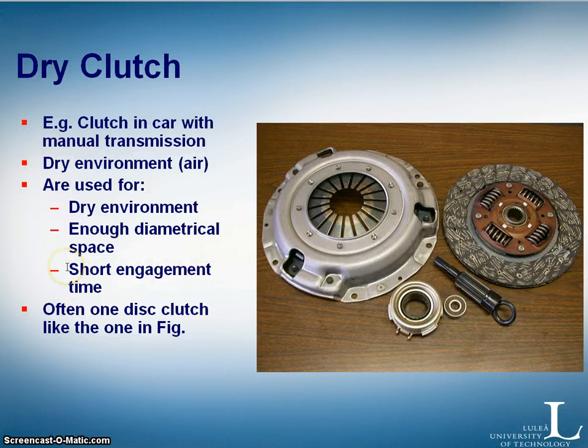And they are used where you have short engagement time, because air doesn't cool the clutch very much, which means that we should have short engagement so we don't produce much heat that we need to cool off. Often we only have, as I said, one clutch disc, and we will see the difference to wet clutches later on.